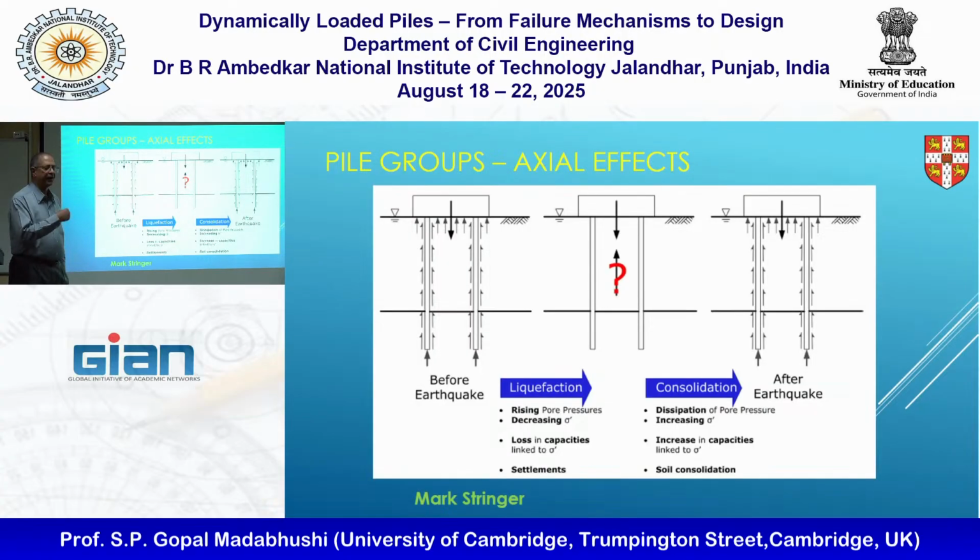Okay, so if I ignore that, otherwise what you have to do is to take the cap area, subtract the areas of the piles themselves, and work out your normal shallow bearing capacity factor, and say that is going to be an addition. And the reason people are not so sure about that is how much load that carries depends on the stiffness of the piles, how much end bearing, how much settlement I got.